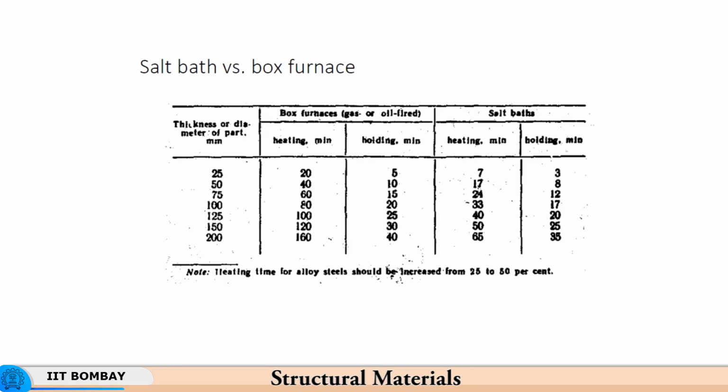Now, you use what is called convective heating in both the cases, but in case of salt baths, the body of the salt, the amount of molten salt, is far too high as compared to the volume of the workpiece, and therefore you get very rapid heating and retention of the heat for the duration of time it is in, and so the time needed to equalize the temperatures at the center and the surface is much lower.